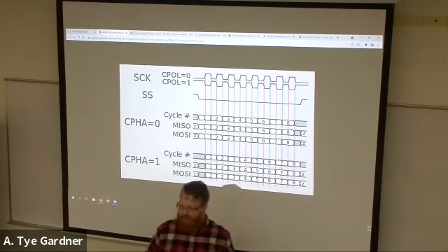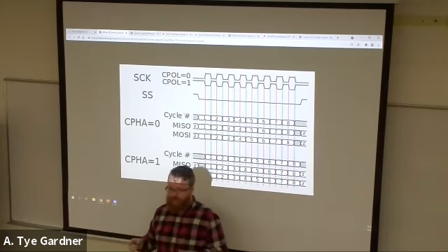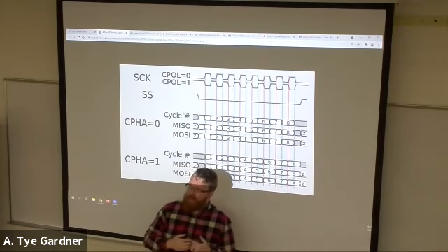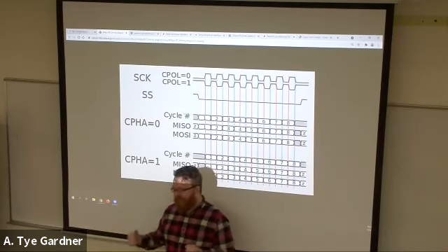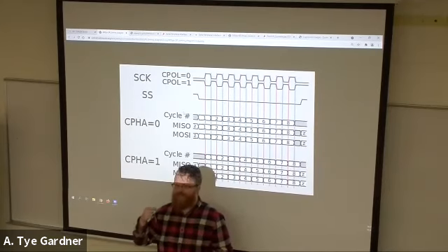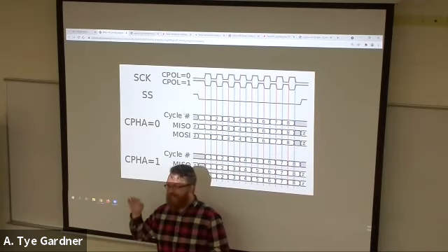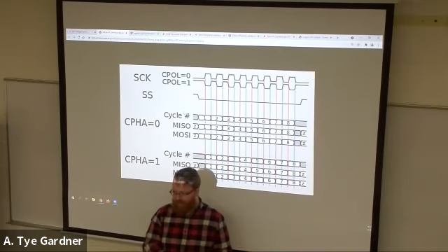In fact, we had someone in here with one of their labs in the UART where 30 out of 31 times it was the right value. And then it would tick over and be the wrong one occasionally, because the race was won by the clock most of the time.